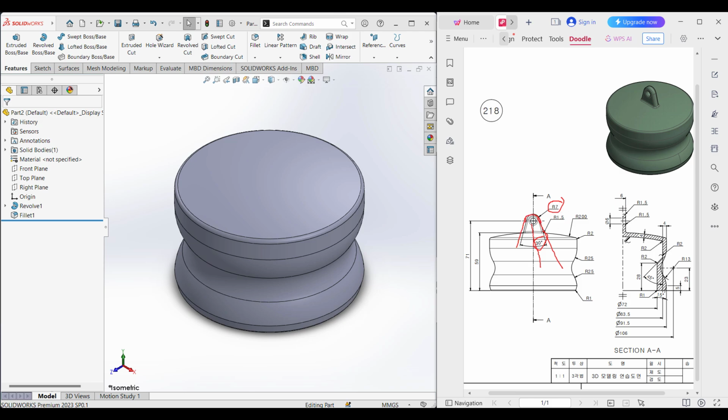After that we can see it has a cross section of AA here. It is extruded to 6 unit. So I'm extruding it from the mid plane 6 unit. Then we can see we have some fillet radius of 1.5 unit here, fillet radius of 1.5 unit here, and fillet radius of 1.5 unit here.